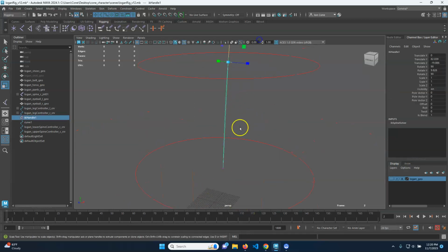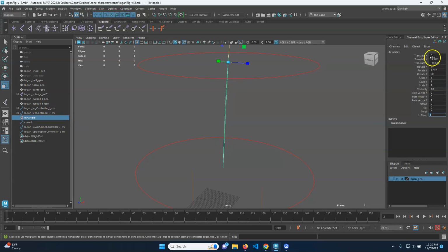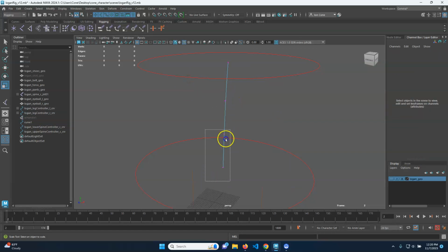Okay. So what I'm going to do is right click, go to control vertex, and I want to select, you will see there, that stupid handle's in the way. I'm just going to turn it off. You don't have to turn yours off. It's going to turn off so you can see a little better. So you'll see there's 4 of them, 1, 2, 3, 4. We're going to take the bottom 2 and more or less parent them to this. Take the top 2, parent them to this.